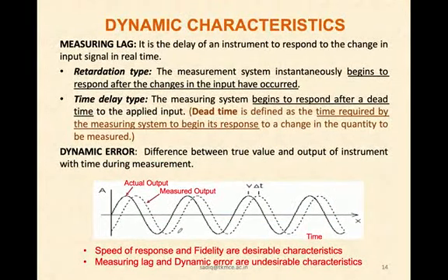Another dynamic characteristic is measuring lag. Lag, as you know, is a delay. Lag means the delay of an instrument to respond to a change in input signal in real time. Real time means when the instrument is actually subjected to an input signal, and how much delay it takes to respond to that. That is called measuring lag.